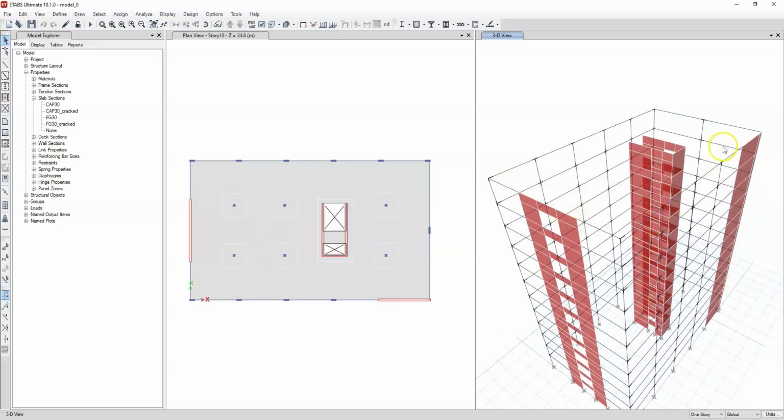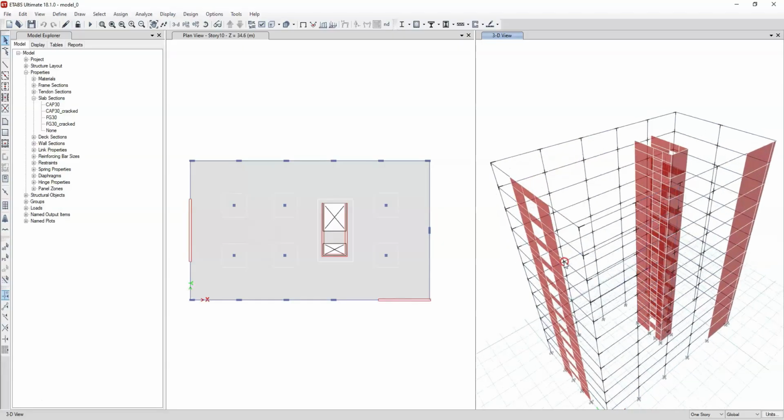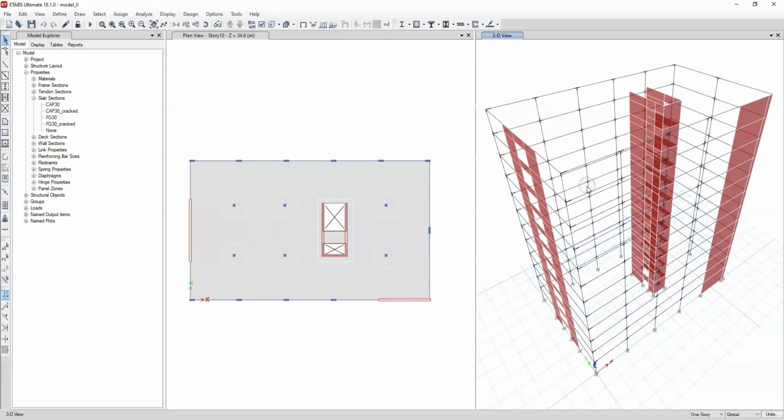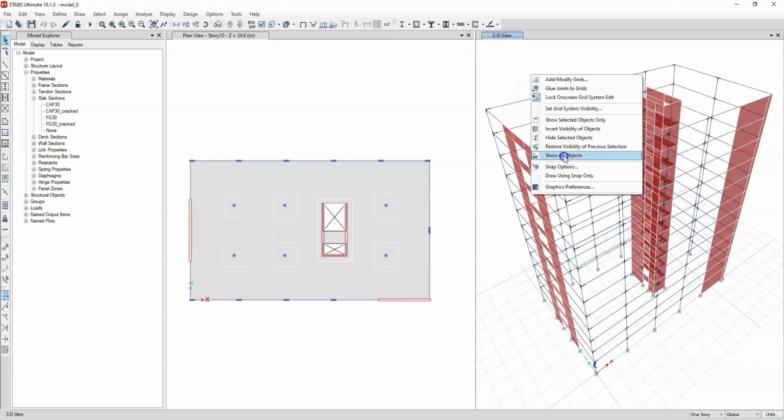In other words, in different directions, a frame may be primary in one direction and secondary in the other. Frames and walls are primary structures when they are bending about their major axis, highest inertia. In the opposite direction, we have a secondary structure. Naturally, all other elements, the central columns and the waffle slabs, and their connections to columns, are considered a secondary structure regardless of the direction.